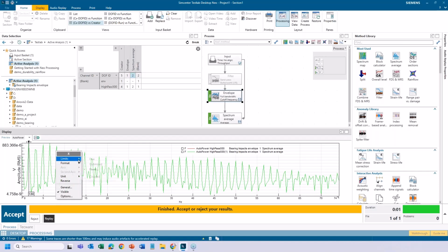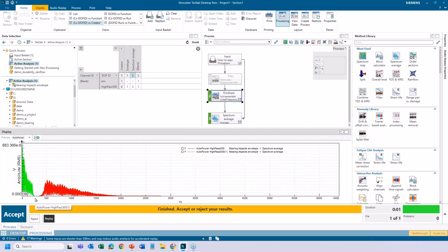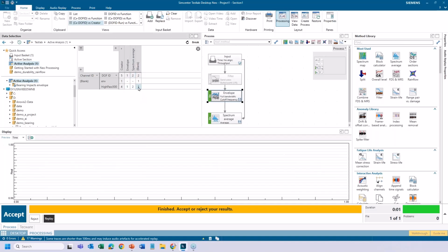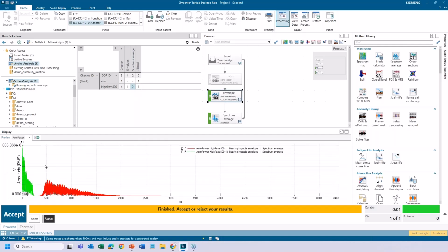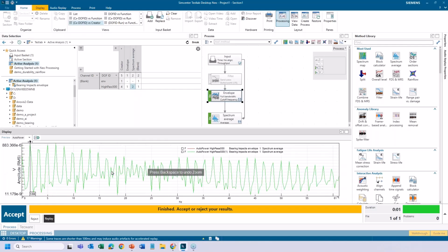Each impact event, and this is kind of a weird thing to get your mind around, each impact event really is a high frequency event, right? It's a very brief impact, short in time, so it has broad frequency content. It consists of a very broad range of frequencies, the individual impacts. But the rate at which they occur, every so often in time, that's very low, 1.6 times per second. And that gets reflected then in the FFT of the envelope. We can pick up the frequency at which the impacts are occurring.